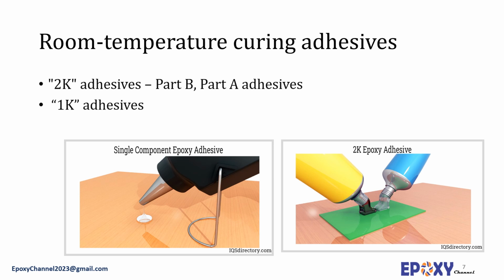In these formulations, very reactive curing agents are employed. Curing is again an exothermic reaction, and the amount of released heat is dependent on the formulation and the mass of adhesive that is mixed. Room temperature adhesives can reach their full strength in a short period, for example a few minutes, or even several days, for example 5 to 7 days. This period is determined by the type of the employed curing agent. However, most common room temperature curing systems are cured in 18 to 72 hours to reach full strengths.